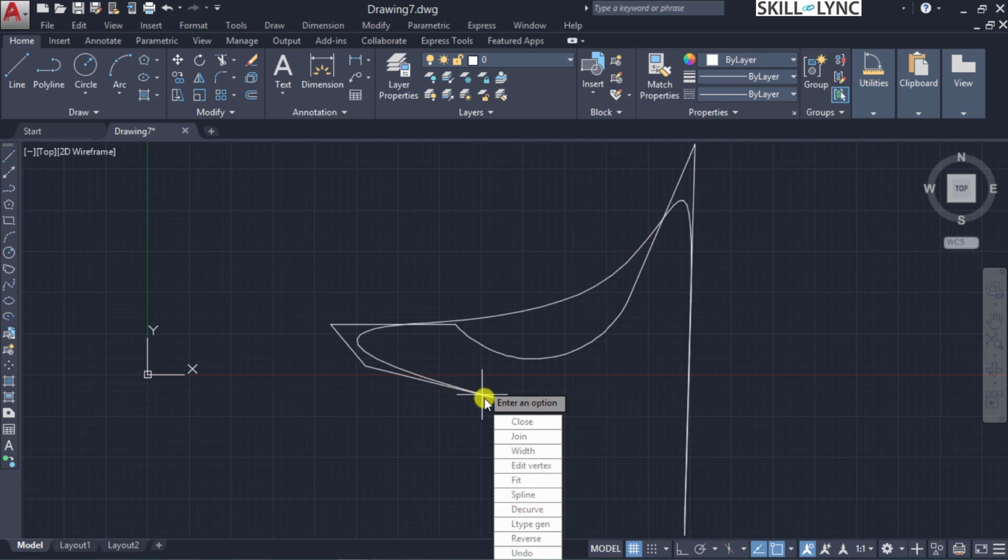What it does is the source point and the end point are maintained the same, whereas this spline will tend to be pulled towards the vertex point. These vertexes of the original curve tend to act as control points, and thereby they will control this spline curve. Using this spline, we will actually get two types of splines, either a quadratic B spline or a cubic B spline. These curves will be different from what we are currently using, this fit curve. There's a separate option called spline variable, which we will look at in a subsequent curve.